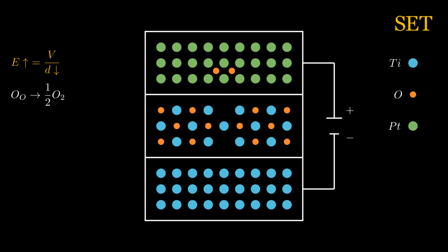Due to the very high electric field, the oxides of the switching layer migrate to the top electrode and accumulate at the interstitial sites near the interface. As soon as the oxides leave, vacancies form at their preceding sites. The oxide releases its electrons after reaching the top electrode, and the electrons go to the positive terminal of the power source. Electrons released from the negative terminal go to the bottom electrode.